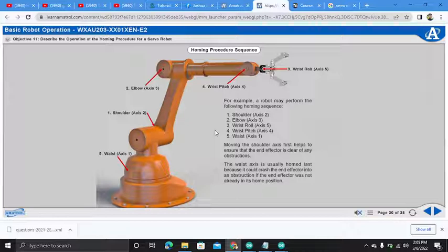The closing movement of a curvilinear two-point gripper is a circular path because the fingers are jointed from a single pivot point around which they rotate. The two-point curvilinear gripper is often pneumatically powered.